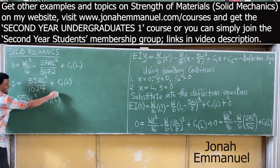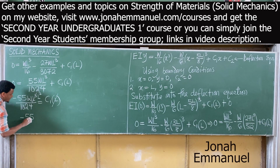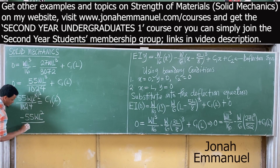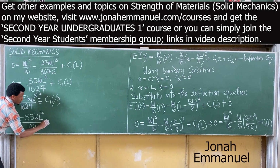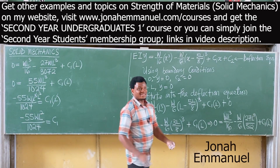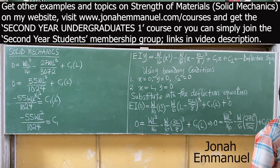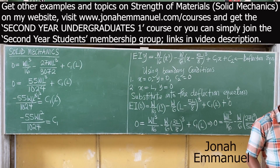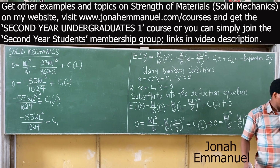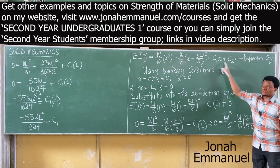From here, you can see that L will cancel. L cube will give you L squared. So what do you have here? Minus 55 WL squared all over 1024 is equal to C1. We've almost answered the first question. The first question is to find the equation of deflection. You can't stop here. You have to find the value of C1 and C2.